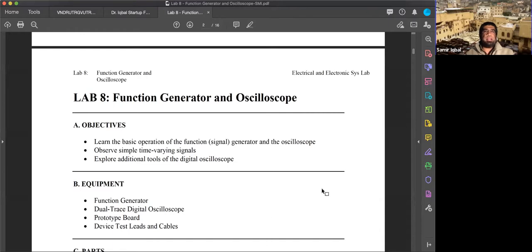So if its maximum is 2 volts, which would mean either it is going from 0 to 2 volts, again 0 to 2, or it is 2 volts peak to peak, in that case we would say it is going from -1 to +1 volt. And it's alternating between these two maximum values. Now, how fast is it alternating? That's what would give us the concept of frequency.